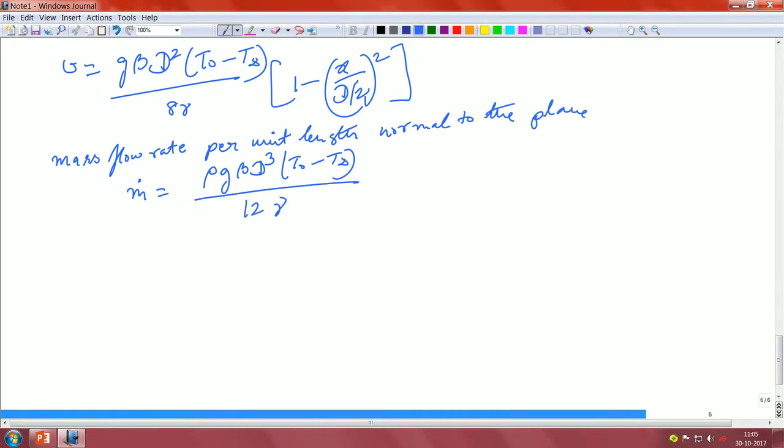Okay. So, m dot basically we have found it through rho a into Vm. Vm is the average velocity. In order to calculate the average velocity, you need to just integrate this guy, right. That will give you rho a into the corresponding Vm. That is how that integration you can do as an exercise. It is just integration from 0 to d by 2, right. So, that is all the integration there is to it.